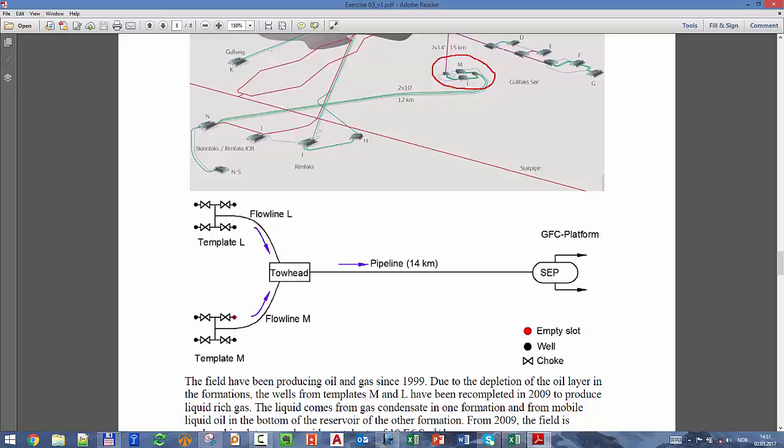But then, if I'm given the rates, I have to calculate the choke, which will be my equilibrium point: pressure upstream of it, pressure downstream of it, and the difference should be positive. So how do we do it in our sheet?